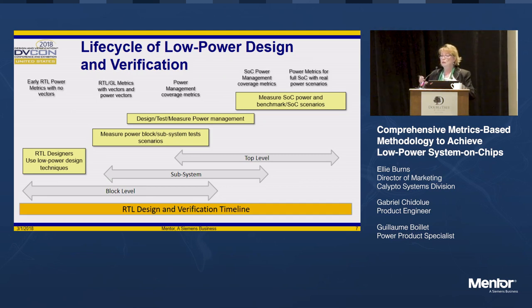And then as we get bigger and start putting together bigger SOC designs, I want to look at SOC power management metrics. So look at the whole UPF along with the software and everything in the controller. And then at the end, I really need to measure the power of the full SOC under critical scenarios, because oftentimes that is where your product is going to be measured: can you meet the power requirements of running certain critical benchmarks. So I think you need to look at this very holistically from the beginning to the end in order to meet your power budgets and have a competitive product.